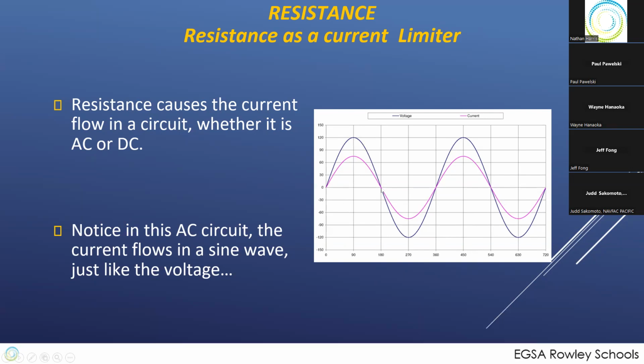So here, both the current and voltage are zero, and the amount of power you make there is zero. Here, both the current and the voltage are at max, and the max power is made. And how that works out then, as long as everything stays in sync like this, taking RMS voltage times RMS current is going to give you the RMS power that's really available to come out the back end and use for your equipment. We'll get into later cases where this is not true.